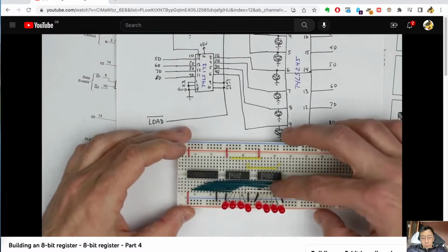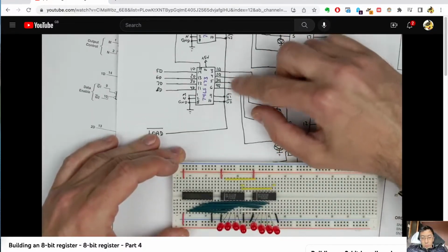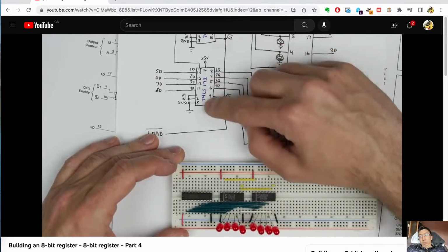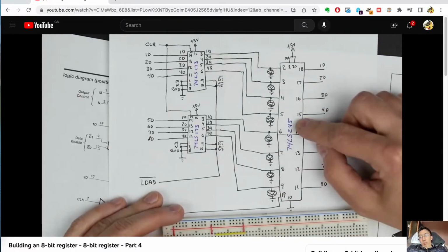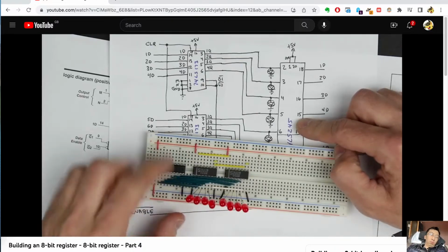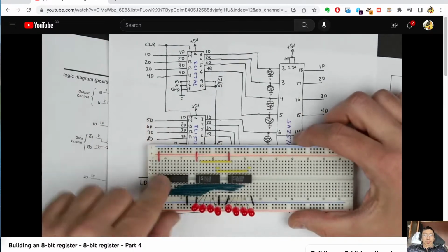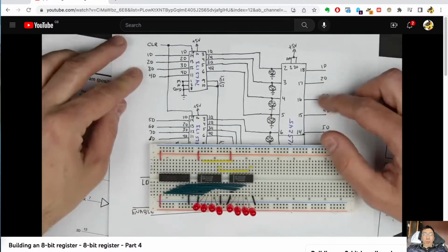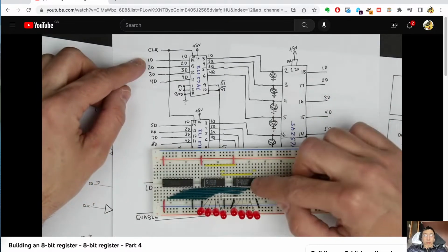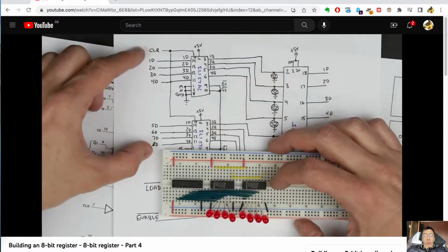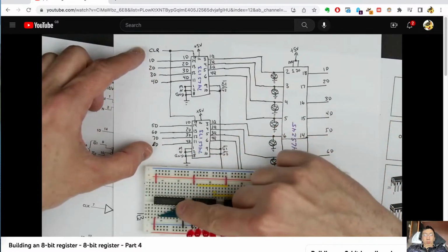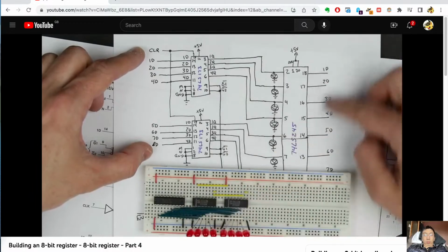We've got this hooked up now, so that all of our outputs here from the 74LS173 register chips are hooked to the 8 inputs across our 74LS245, which is over here. So the other thing we should do is tie the bus terminals here together. Each of these 74LS173s has 4 connections to the bus, and so across both of them there's 8 connections to the bus. And then the 74LS245 buffer here also has 8 connections to the bus.